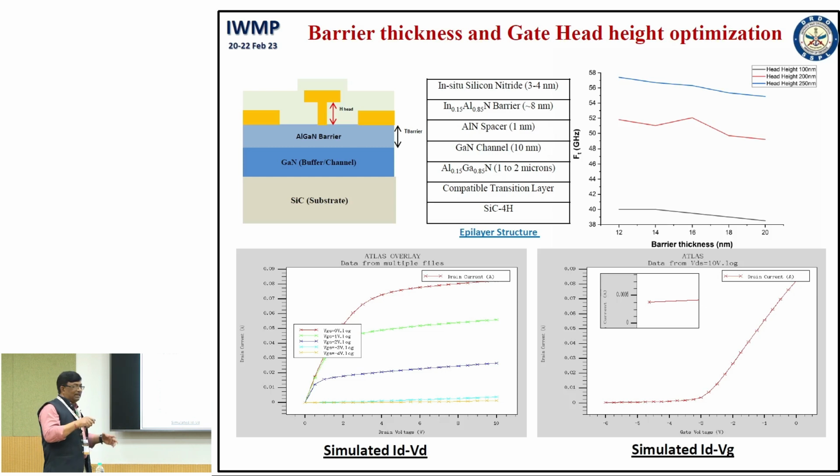So, there are different techniques. This is called gate engineering. By introducing the desired T gate shape, you can control the parasitics and enhance the frequency performance.